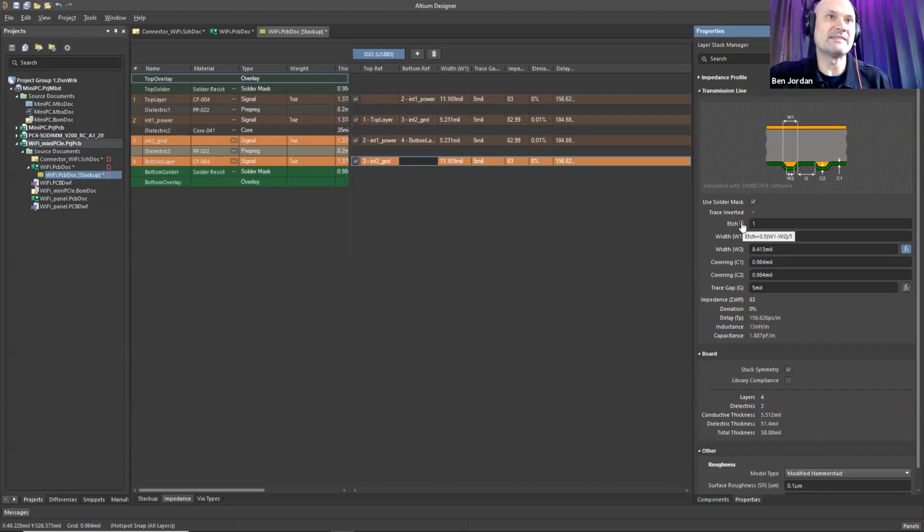It's half times the base width minus the trapezoid width over the thickness. And that's from the standard, industry accepted etch factor, which you would know if you're a CID, you would have studied that in the CID training class.